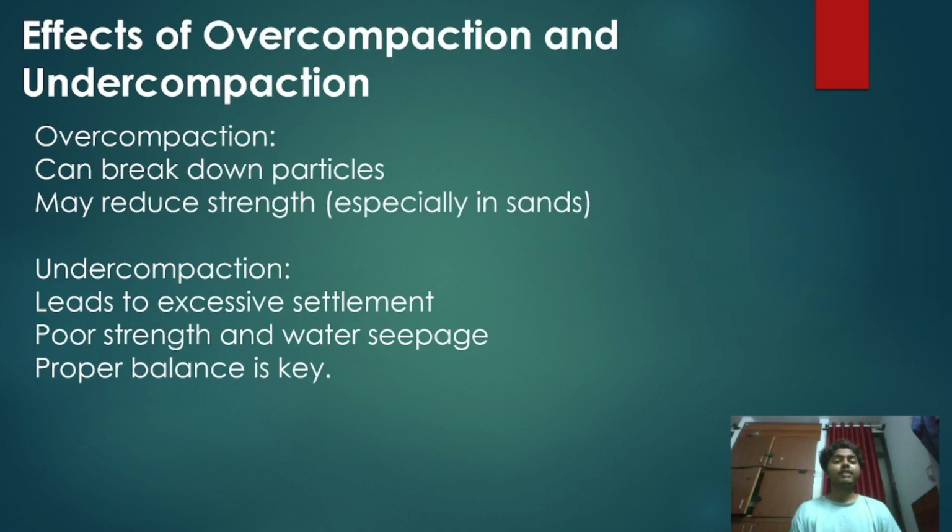And what are the effects of overcompaction and undercompaction? This point is also important. Overcompaction can break down particles and may reduce strength, especially in sands. Undercompaction leads to excessive settlement, and second, poor strength and water seepage. So proper balance is the main key here.